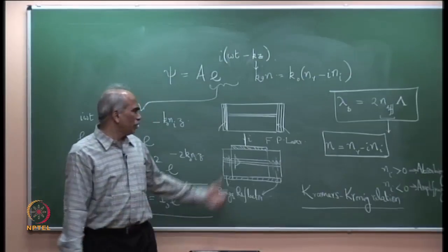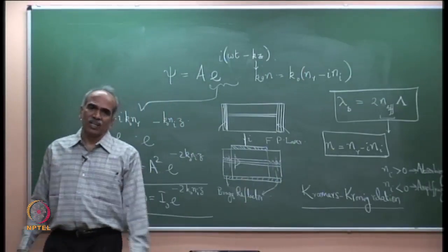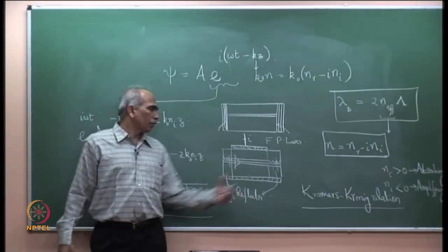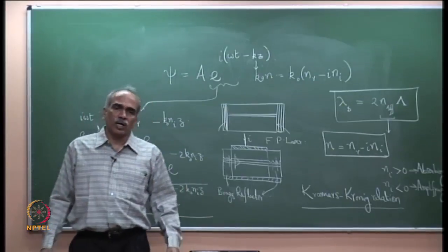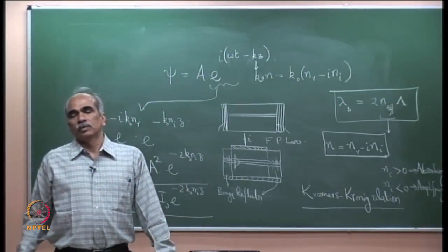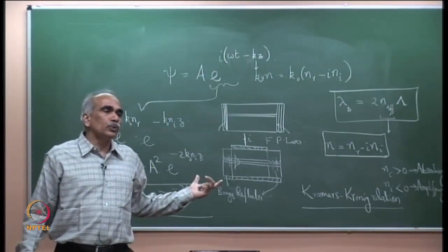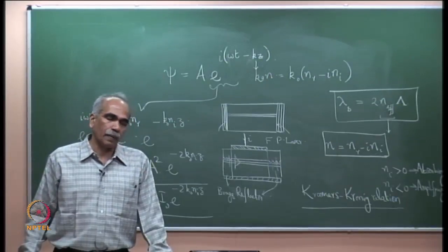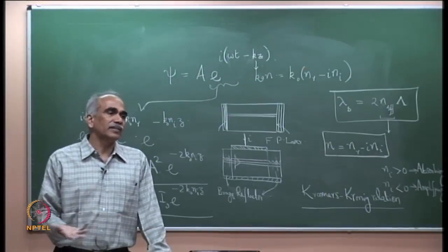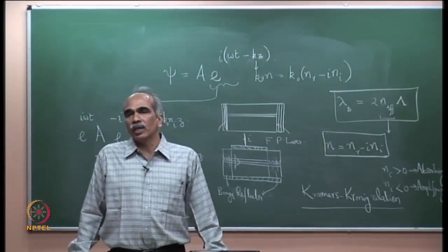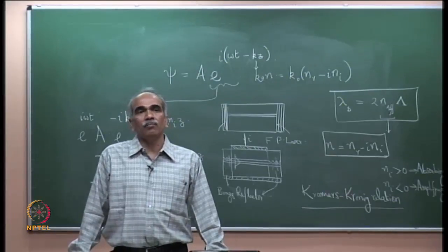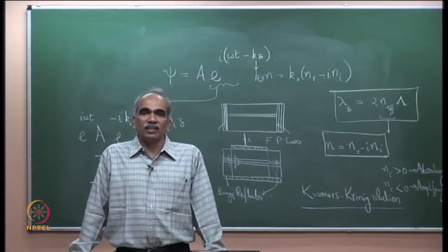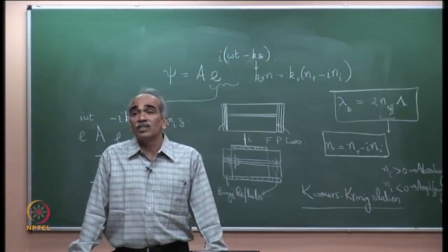However, it is a little bit more difficult to fabricate this at the ends, and normally unless you really have an application where you require extreme high stability of the laser frequency, we tend to use DFB lasers. Therefore, in communication we normally use DFB lasers because the current system at least uses the on off keying or intensity modulation scheme, and therefore, it is not an issue. However, if you use coherent systems, then this will become an issue. The frequency shift will be an issue.